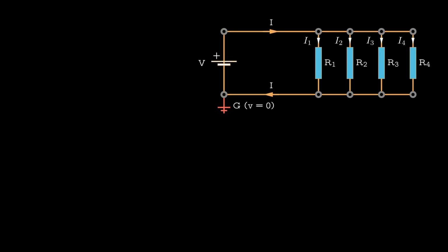In this section, we are going to find the equivalent resistor for a network of parallel resistors. Resistors R1, R2, R3, and R4 are connected in parallel to a voltage source V, with one side of the voltage source connected to the ground. By connecting one side to the ground, we ensure that the voltage at this point is zero, which simplifies the circuit analysis. I recommend following this best practice when analyzing circuit diagrams, as it provides a clear reference point.